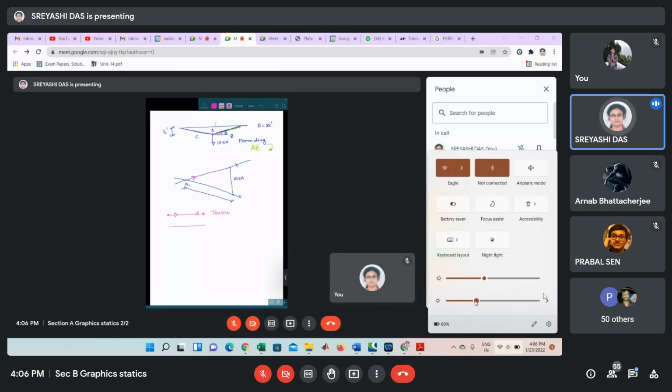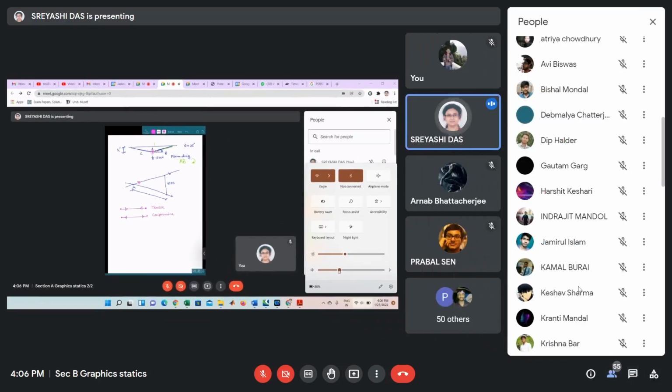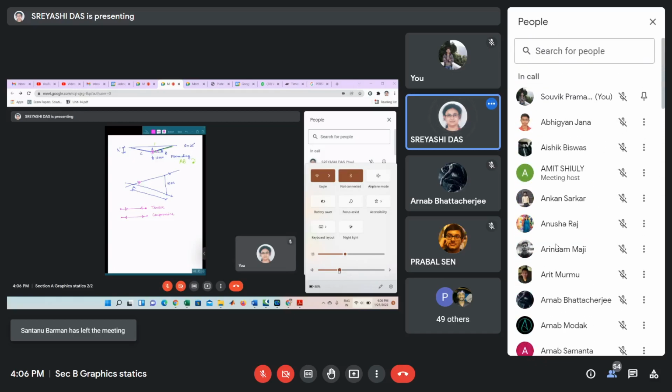And if the force is acting like this, that is towards the joint, it is a compressive force. For this case, in the form diagram, if we take this joint, we can see that the arrow is actually away from the joint.